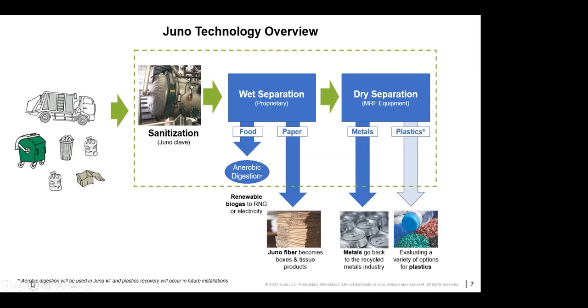And our product currently, since we are at a containerboard mill, we do bale and wrap this material because they did not want to receive raw garbage at the facility. So we feed these bales. Approximately 25 tons of material goes into a batch. We apply steam and pressure to it, so we sanitize the waste. We don't sterilize it because we're at low severity.